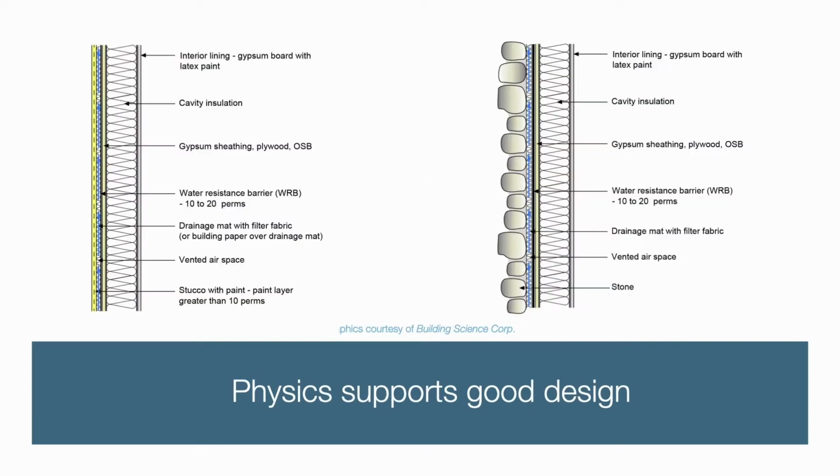When we look at these details, this is a part of a graphic from Building Science Corp. You can see the picture on the right and the picture on the left, but these ideas showing stucco and stone applied claddings, for example, on a scratch coat, all represent reservoir cladding systems. And you'll see in all these assemblies, it talks about how critical it is that there's a scratch, and however we decide to layer those up, whether they're single scratch, brown and finish, or whether they're just two-layer systems. We have this in various climate zones.